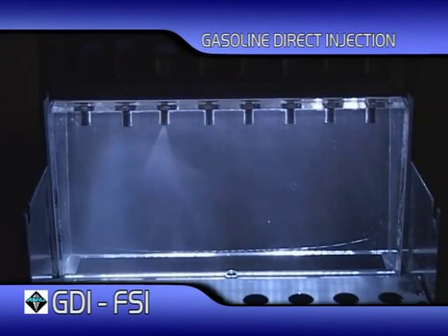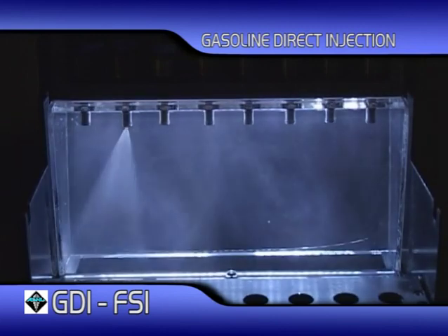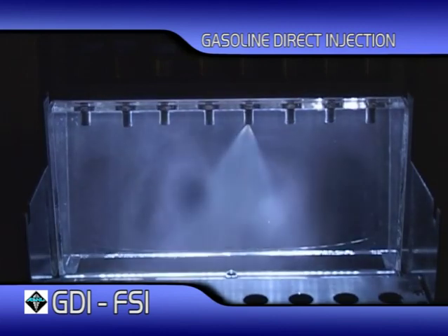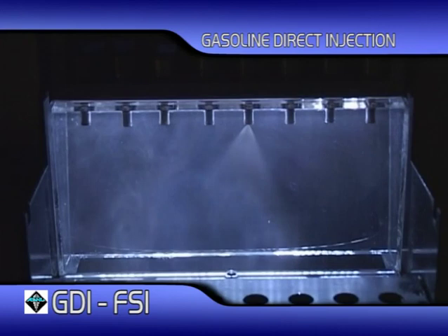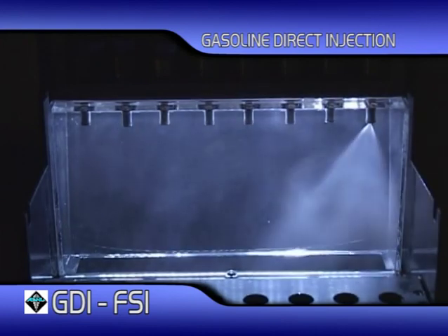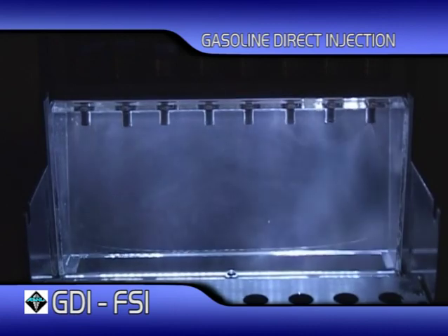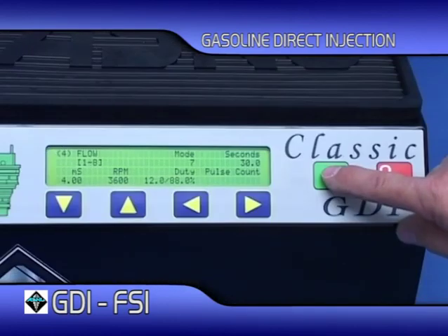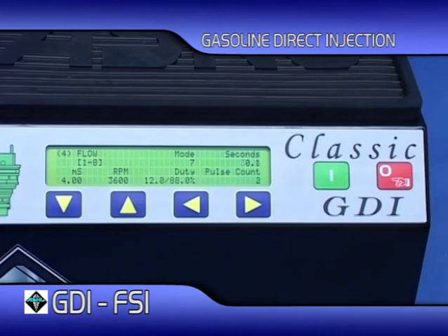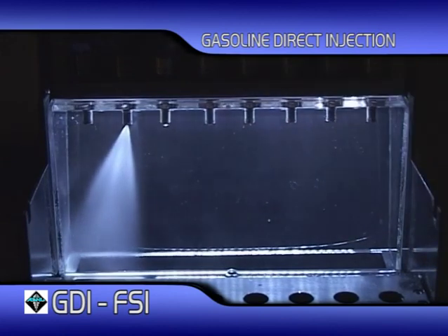The vehicle's GDI system operates at a potentially dangerously high fuel pressure, varying up to 200 bar. With the injector opening for short microsecond durations, with a maximum opening duration of only 5 milliseconds, any visual spray analysis could be both difficult and dangerous. The ASNU allows the user to safely examine in greater detail the injector's spray pattern for any discrepancies in the fuel distribution and atomization. For ease of use, in some operating modes the ASNU system opens the injectors for a much longer duration. The injectors can be operated at various RPM and millisecond settings, restricted only by the number of injectors being tested in the sequential testing operation.